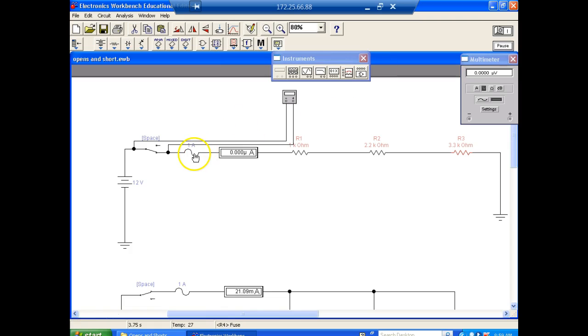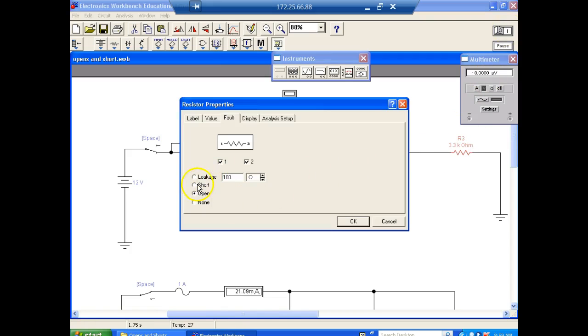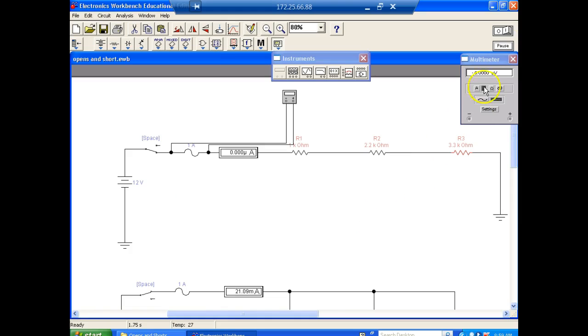I didn't show it, but what happened? Yeah, the fuse blew. And of course, to check a fuse, normally what we do is we come over here and measure across it, right? And if it measures the applied voltage, then that means it's what? Yeah, but it's not doing that. You put an open. Oh, I did? Oh, thank you. This will blow the fuse. Okay. See it blow? And of course, what's across the fuse? The source of it. We're using the 12 volt supply right there.